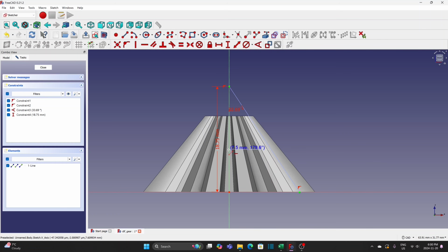Draw a horizontal line from the y-axis to the construction line (10 mm long). Draw a straight line. Snap the point to the line. Make these two lines perpendicular so the back angle is the same as the pitch angle.